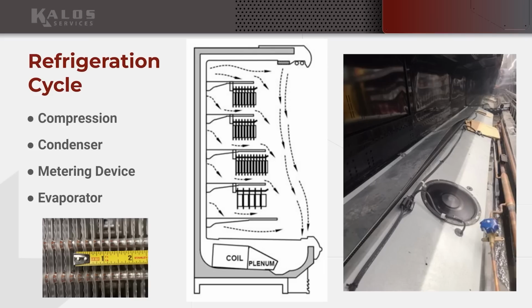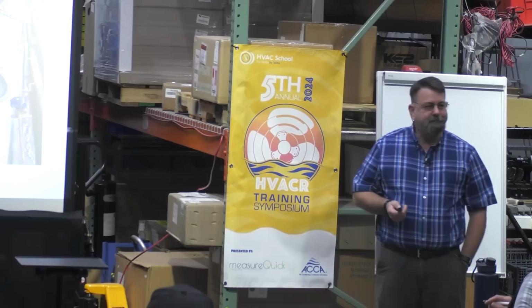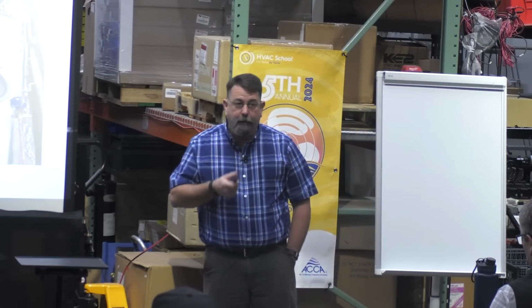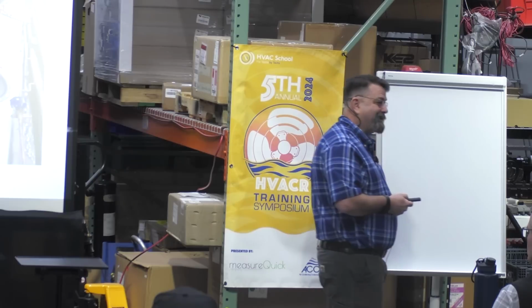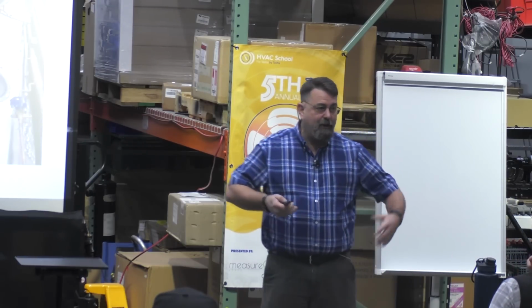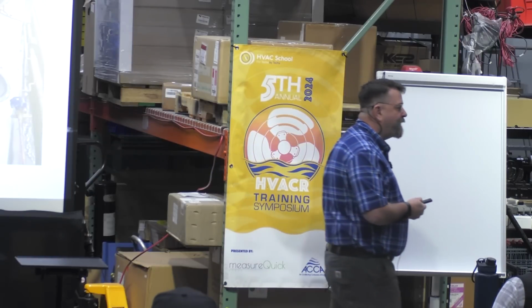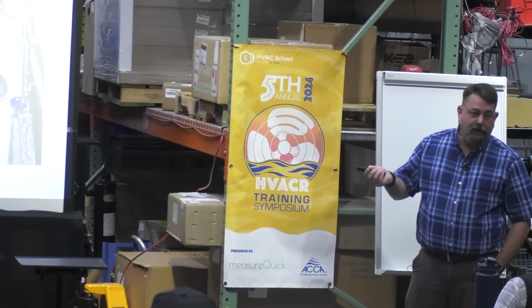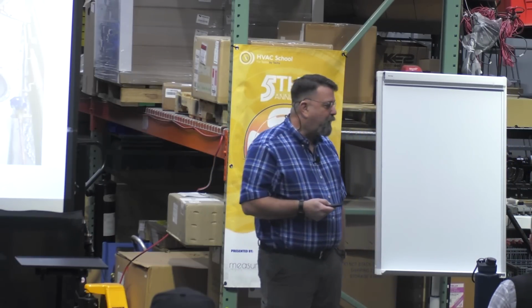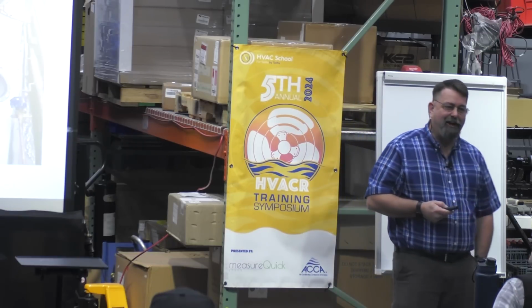All right, so something else we're going to see on our evaporator are fins. As you guys probably know, the more fins I can cram in per inch, the more efficient the system is, right? The less energy it requires to do the same amount of work, because you're making the evaporator bigger by having more surface area. But there's a downside to that. You can't go too far. In residential, that's probably limited by dust and cat hair, right? You start stopping that thing up.